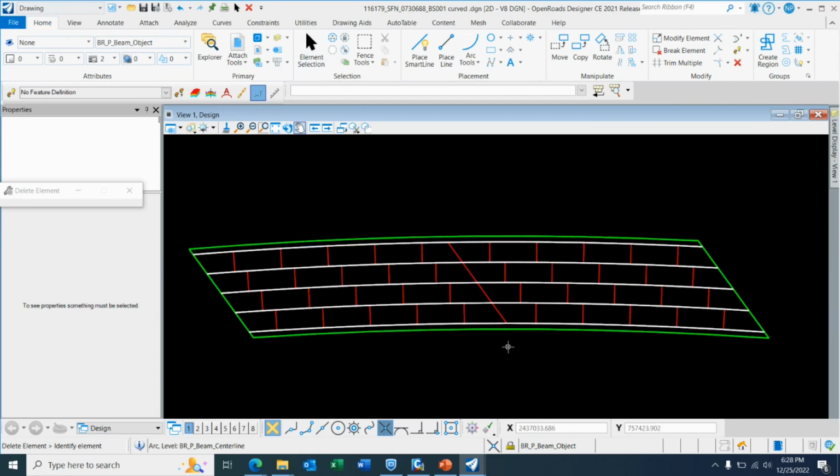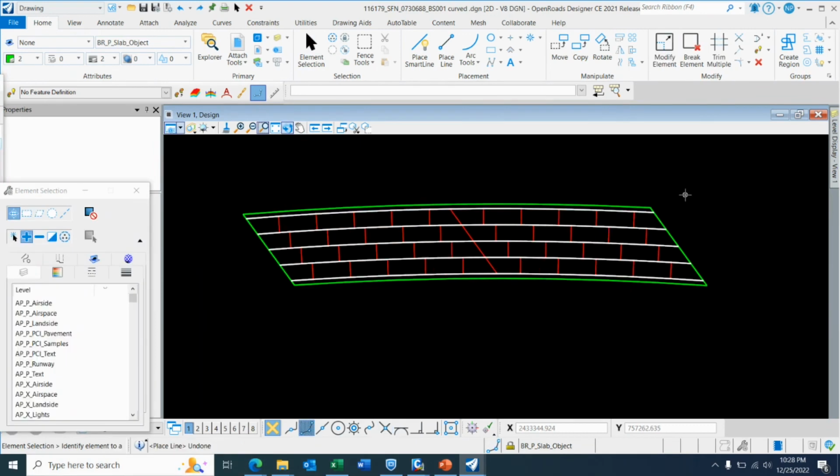And now let's talk about the cross beams. Since we are using the Grillage method, we need transverse members, also known as cross beams, to transfer load from the deck. Basically, it should mimic deck rigidity or stiffness, but not the weight. The common approach is to use cross beams that are 5 feet wide, but you can use any width of those cross beams. But I'm going to use 5 feet for this example.